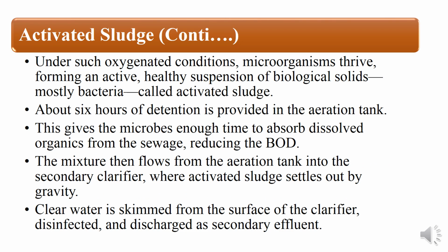In the activated sludge, under such oxidation conditions, microorganisms thrive, forming an active, healthy suspension of biological solids, mostly bacteria, which is called activated sludge. About 6 hours of detention is provided in the aeration tank. This gives the microbes enough time to absorb dissolved organics from the sewage and reduce the BOD.